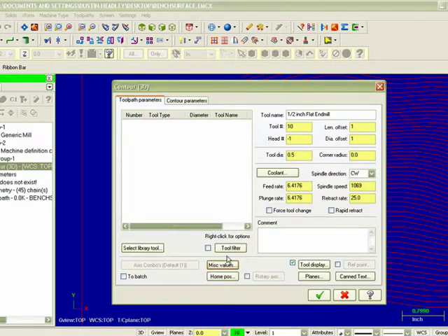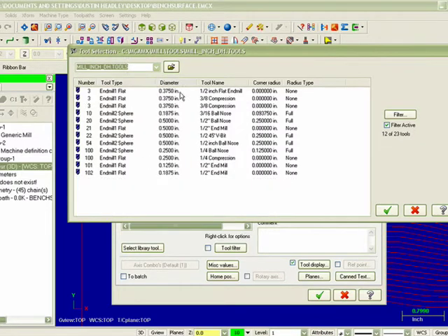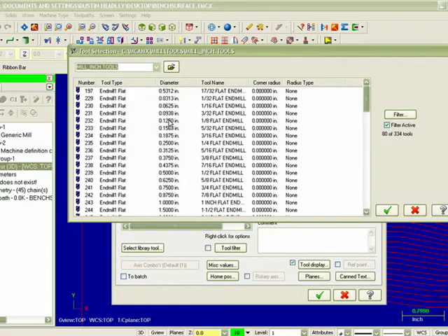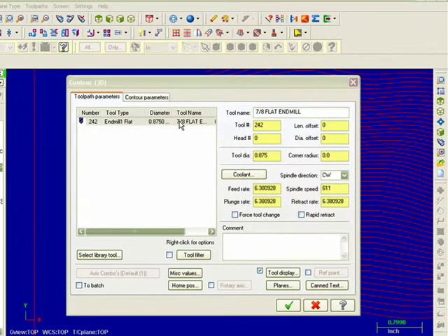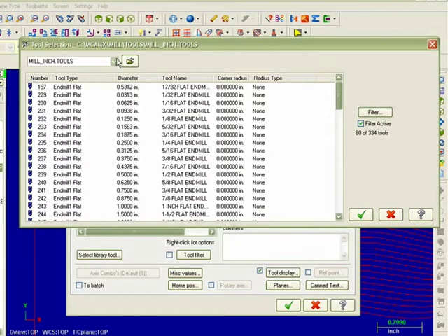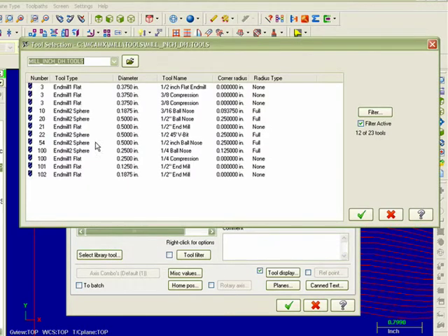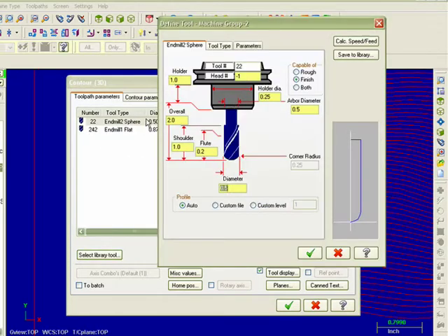And now we're here in the toolpaths, this parameters portion of this. Alright, and we need to select a library tool. We're going to hit this, and there are all these presets in here, and I've developed my own library, so we can go through here. These are all derived from different tools. If I go in here, I can set these tools, grab one of these, and if I double click here I can edit it, and I can edit those parameters. But this particular project was done on a V-bit, which I have programmed in right here, and let's go in and edit this.